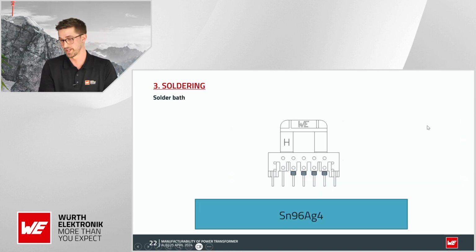To give you a short break, I will now present this nice animation. Check how deep we must submerge our parts into the soldering bath. We cannot use lead to solder due to RoHS directives. Therefore, the soldering bath must be hot enough to melt the tin and the layer of insulation which is covering the wires, but without damaging the bobbin.